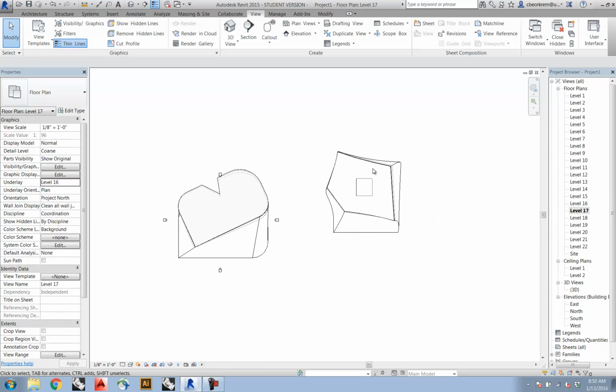Okay, that's all for today. Upload a file that's got a lofted version using 2 different curves or variations on 2 curves on 2 different levels. And then another one where you'd use the X-ray tool as well as a void form to cut away at a given conceptual mass and then update them all. Create floor plates for all of them using the mass floors and then the floor button. And then add in all the levels and a 3D view of your object.